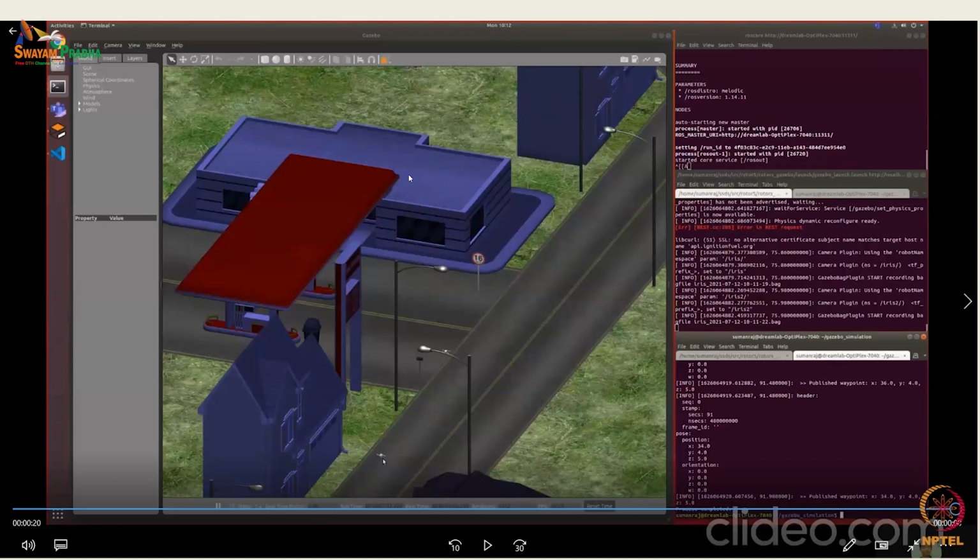Any questions or points that you would like to discuss? The communication between different drones is not simulated in Gazebo, right? Right. If the communication between the drones has to go through a different communication layer, then we'll have to integrate ROS with NS3. That will serve that purpose.